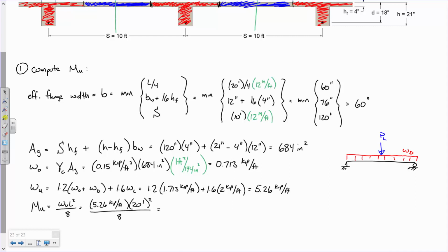That's fine. Now, if you're looking at a girder, you can idealize that girder as just seeing distributed load, or you can idealize it as seeing just point loads from the reactions coming into it. You will get differences on the moment diagram. I promise you. That is undisputed. Two things. Number one, if you have like 6 floor beams framing in, there isn't much of a difference. The numerical difference just isn't that much. And two,